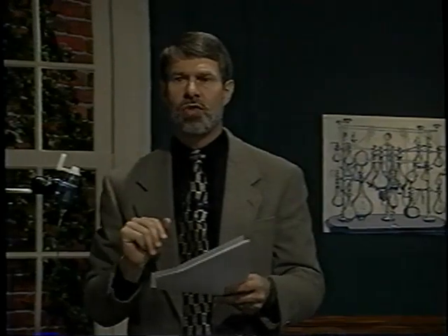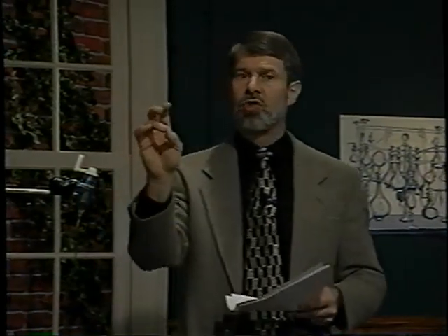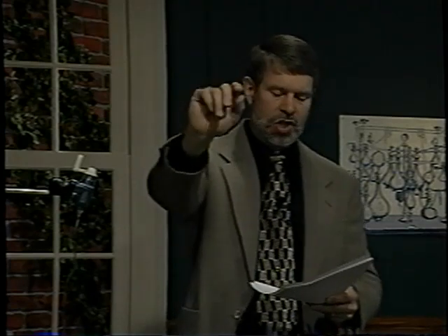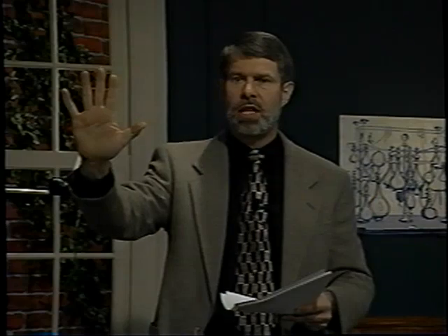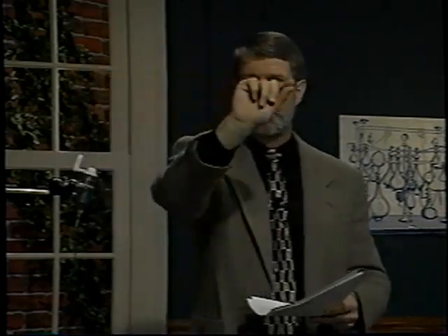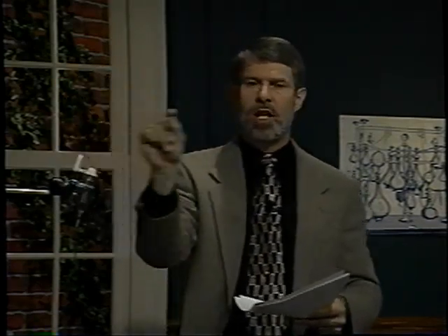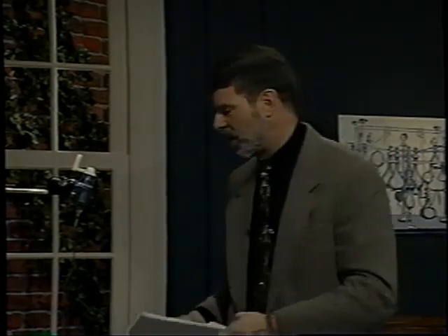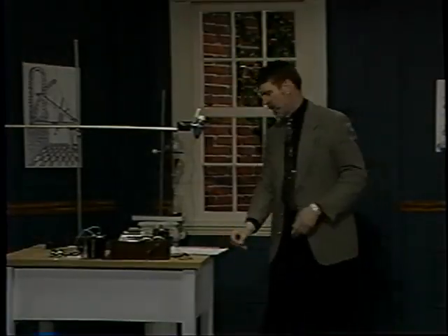Electromagnets are used in so many ways in our lives. In every television set, in every computer monitor, electromagnets control the image on the screen. This is how it works. The image is created when a beam of electrons is flashed onto the screen, and it's rastered across. The electrons strike the fluorescent material on that screen, and the beam is then moved back and forth across the screen to convey information. The way you move that beam back and forth is with electromagnets.